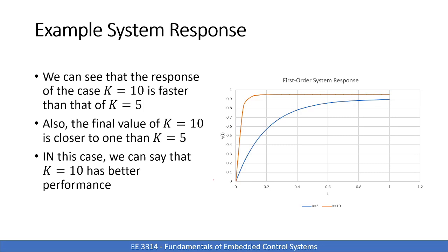Okay, so really what we're trying to do is quantify some of these things like rise time, overshoot, settling time, things that might matter to us in the real world, and how we can quantify those so that we can design our control system. In other words, select our gains or other attributes of our control system so that we meet those desired physical descriptions of the response.